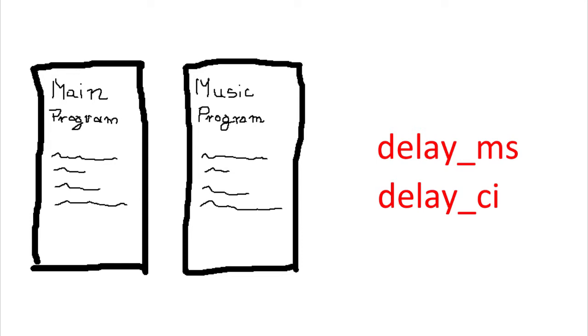These functions will allow the processor to return to normal program execution during this time. After this time has elapsed, the processor will return to executing the music program and will continue to execute it until it is given another delay function, and so on. Do not nest these functions, it can affect all processor operation and cause errors that are hard to spot. It's a good idea to use a macro instead. After the entire music program has been performed, it will automatically go back to the beginning.